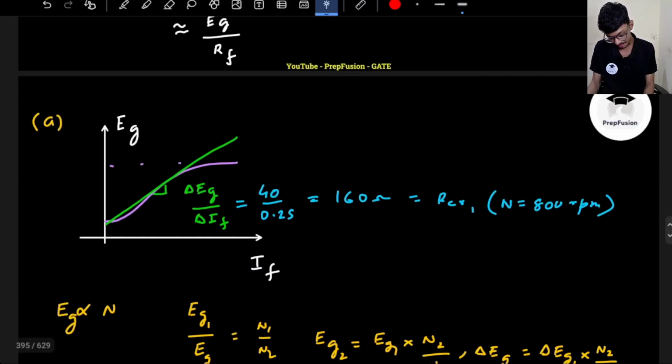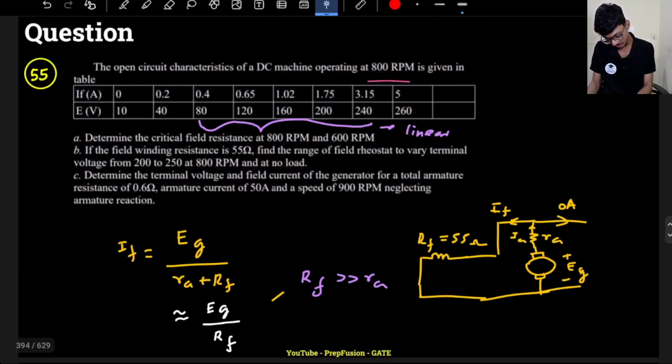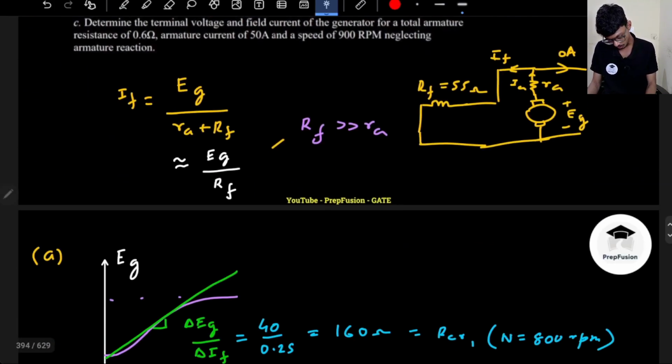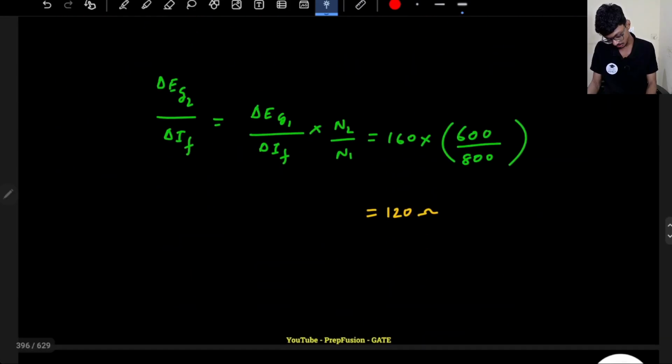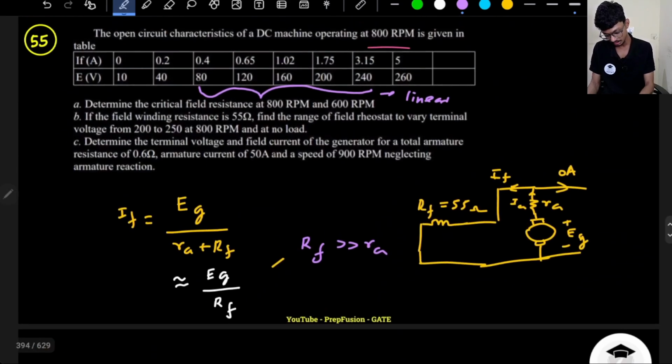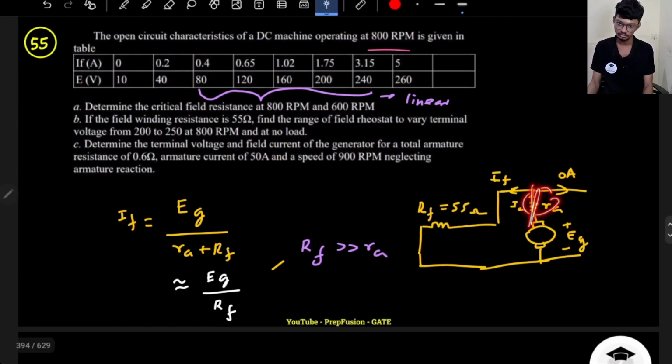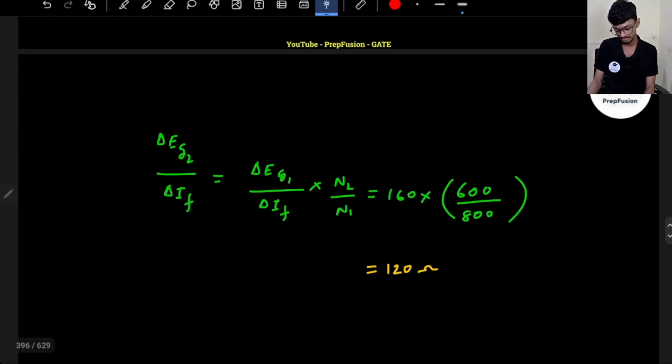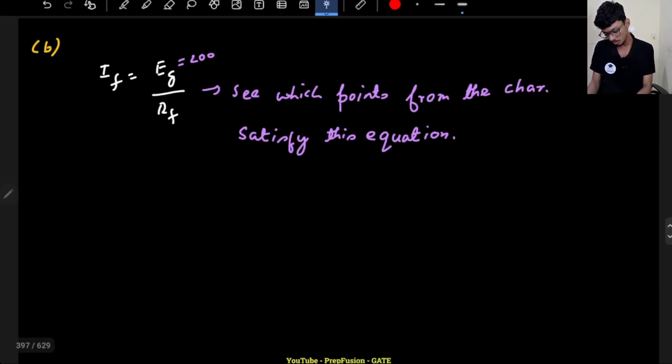Okay. So I just have to plug in values, right? The important point to note here is that 200 volts is already there. That will be the terminal voltage almost, because if I assume that RA is very small, the drop also will be very small, so we neglect it. So 200 I know.